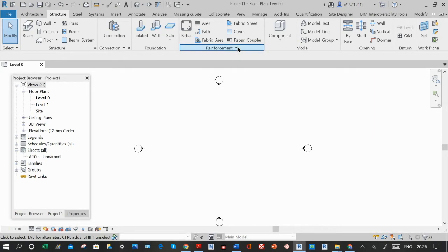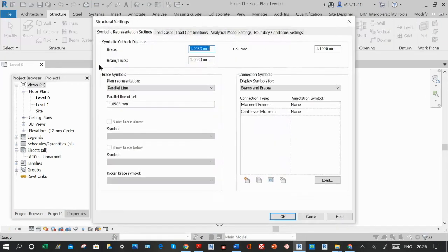To keep a panel expanded while each ribbon tab is displayed, click the push pin icon in the bottom left corner of the expanded panel. Some panels allow you to open a dialog to define related settings. Click the dialog launcher arrow located at the bottom of a panel to open a dialog.